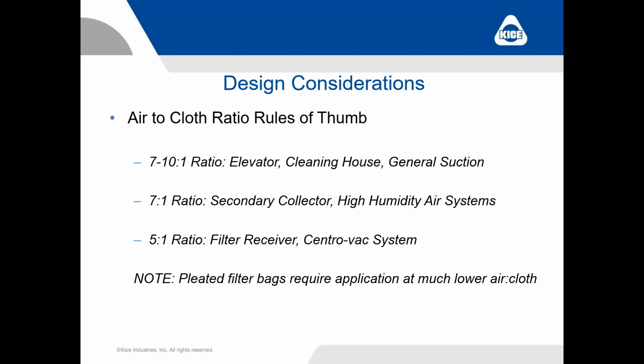The lower the air-to-cloth ratio, the more efficient your baghouse is going to be, the more effective it's going to be, the longer the bags are going to last. But you want to be careful that you don't get crazy and try to have somebody size your baghouse at a 1-to-1 air-to-cloth or a 2-to-1 air-to-cloth. That's really too much filter. That's more filter than you really need. A 7-to-1, an 8-to-1, somewhere in that range is typically a good application number for a baghouse.